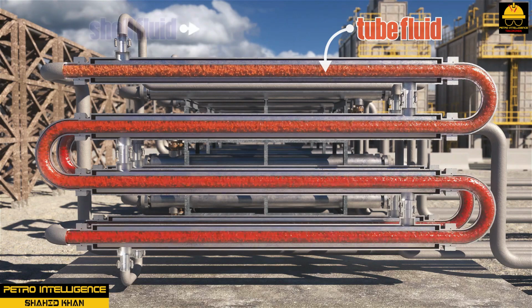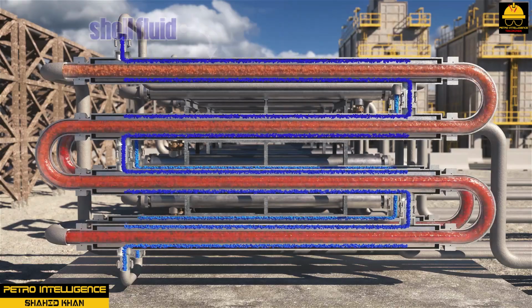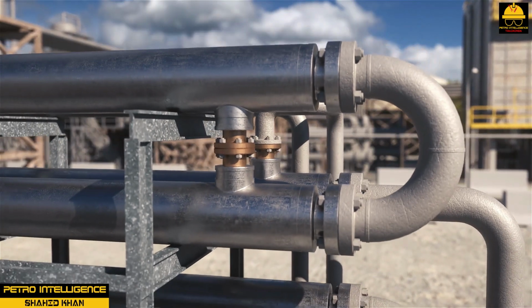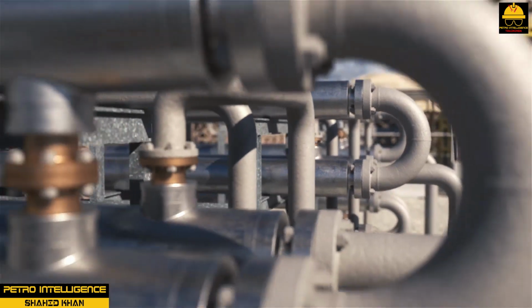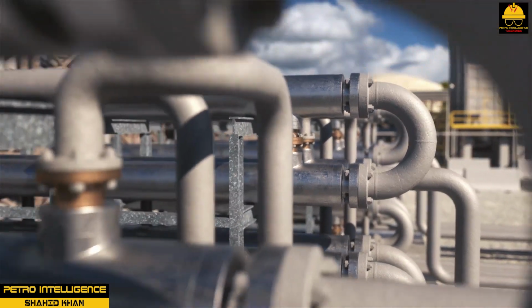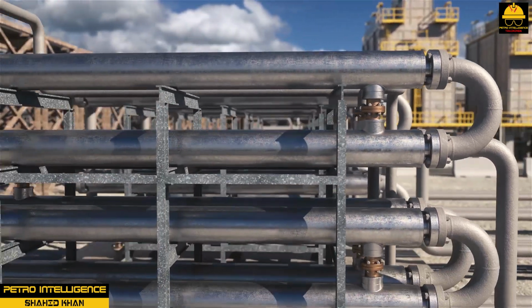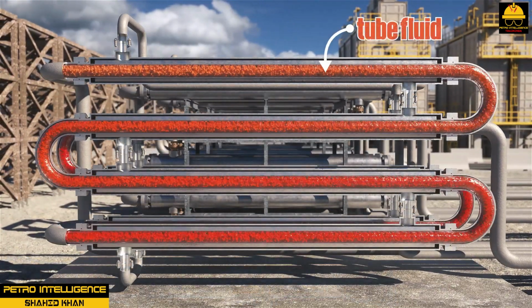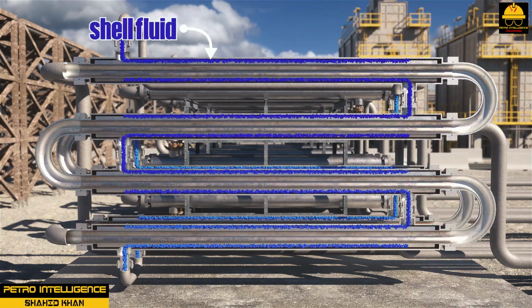This efficiency comes from the turbulent, against the grain, stripping effect of the opposing currents. Even though the two liquid streams never come into physical contact with each other, the two heat energy streams, cold and hot, do encounter each other. Energy-laced convective currents mix within each pipe, distributing the heat. In a parallel flow exchanger, the exit temperature of one fluid can only approach the exit temperature of the other fluid.